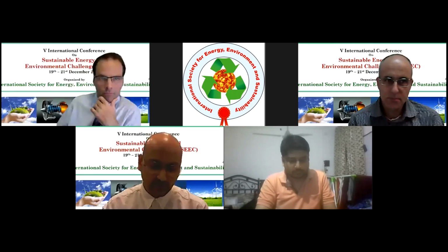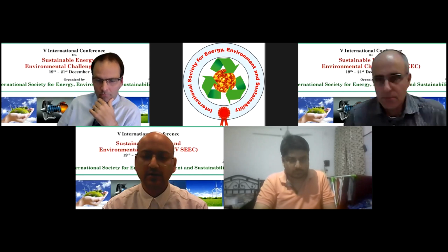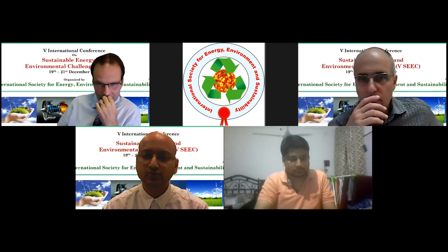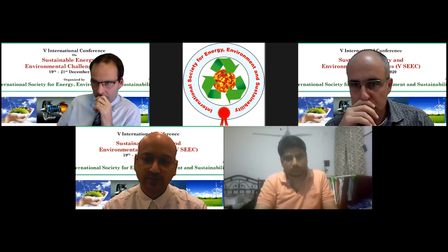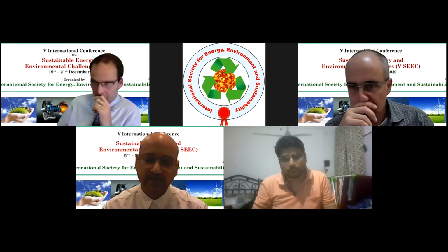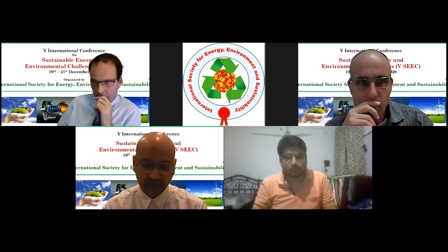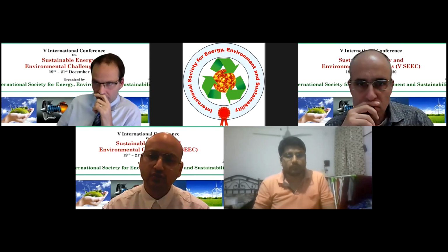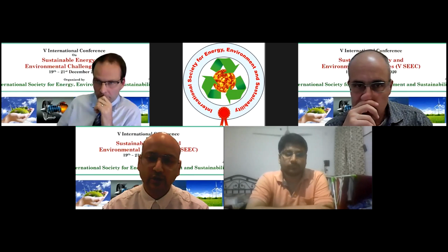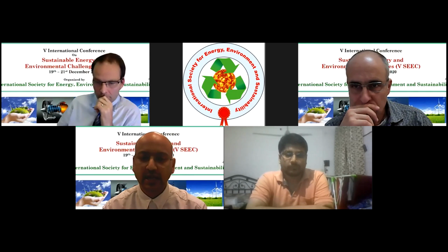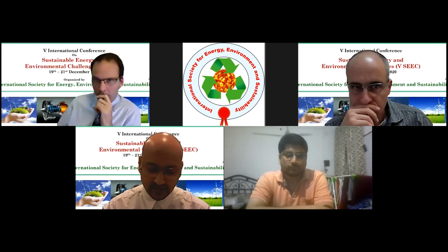And then I talked about different kinds of textures that we can use to control biofouling. Along with other fouling, biofouling is one of the reasons which increases the overall cost of membrane treatment. I talked about how textures can play a very crucial role, and laser-induced graphene and polymer brushes have potential. There are many others, but I talked mainly about these two.